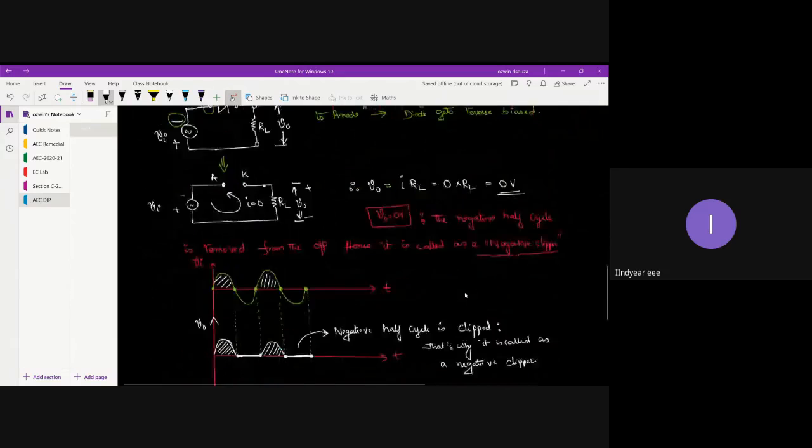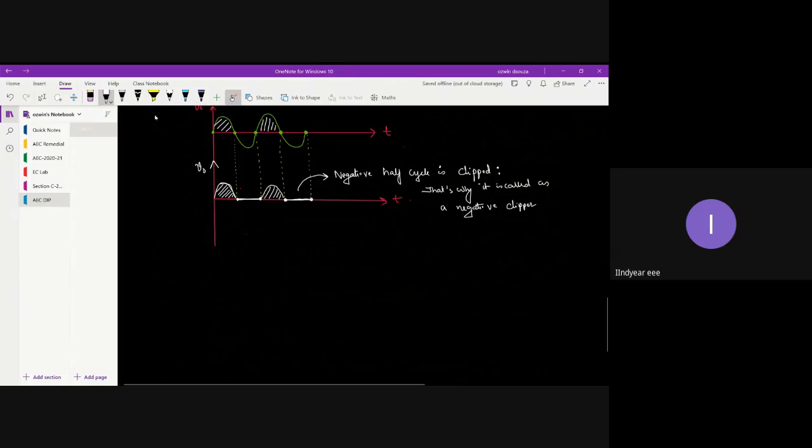Okay, so waveforms you have drawn, and you have been drawing them in your diploma as well. But there is one addition in engineering, that you need to draw the transfer characteristics. I'll tell you what exactly transfer characteristics are. Waveforms are always drawn as signal value versus time, right? Either I versus t or v versus t. In the case of transfer characteristics, we draw the input variable against the output variable. For example, output voltage to input voltage or output current to input current. So that is my transfer characteristics.